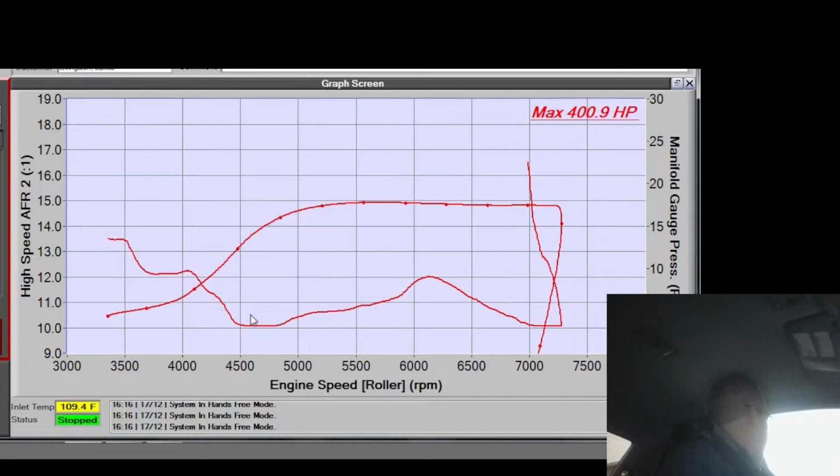I pulled a ton of fuel out right here, and it's still rich as balls. Which means we're really in just wall wetting territory, but it seems weird that this is happening too. This actually moved down now, which is something, but this really feels like resonance in the fuel rails. That's what this looks like.